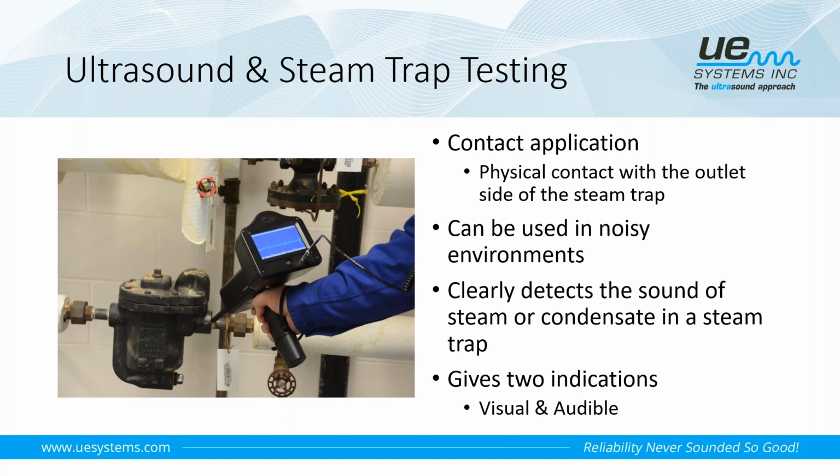We have some high temp remote mounted sensors that you can mount to your steam trap discharge orifice location. Those sensors can either plug in directly to an UltraProbe, or we have some that have other data transfer means, like a 4 to 20 milliamp output that you could monitor or wire into any kind of existing monitoring system. That way we can listen to that steam trap remotely, and we can do it safely, regardless of where that steam trap is located.